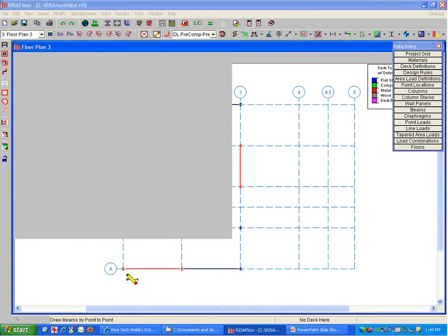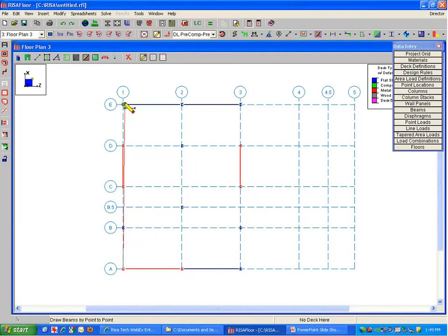And I'm going to say apply, and I'm going to draw that directly across there. And we see here it actually doesn't mess with our lateral beam. It just goes right across and it skips that. And I can click this all the way across, and it goes right across and skips that lateral beam. So you can actually draw two beams on top of each other. It's sort of smart that way. That lets us draw directly across things and doesn't double the beam for us. So I've got those, and I'm going to put one in the middle, and I'm all set for that.